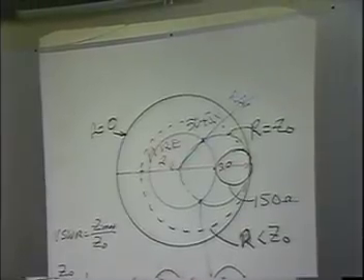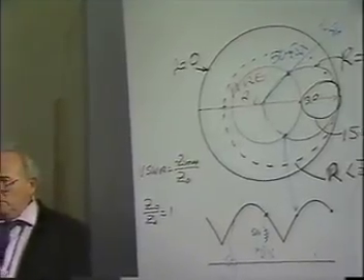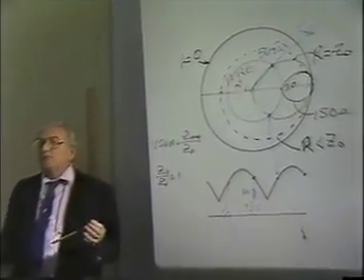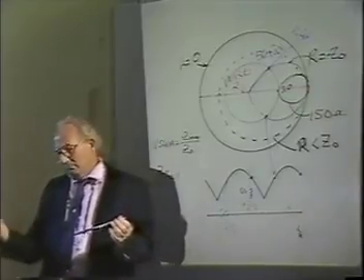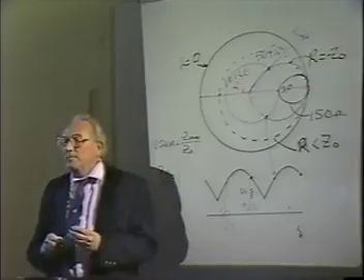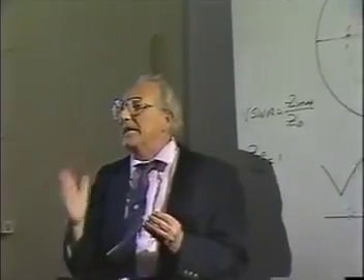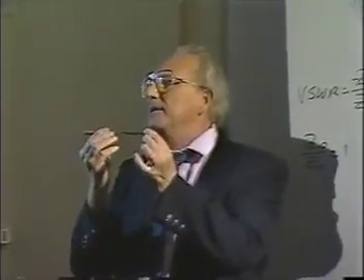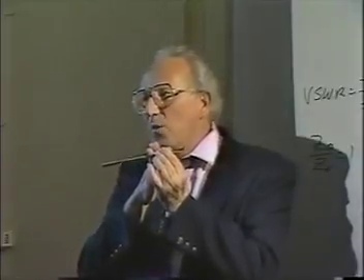Now first of all, let's talk about impedance, which is a series problem. Are you going to work series problems inside of a coax or waveguide? No. Two-wire line? Possibly. Because if it's a series problem, if I want to put an inductance in series to cancel a capacitance, what do I have to do to the line? Open it up, right? And put something in it. You're sure not going to do that with coax. So you know that when you start working inside of coax and waveguides, you're going to be working really with a shunt problem, which is admittance.